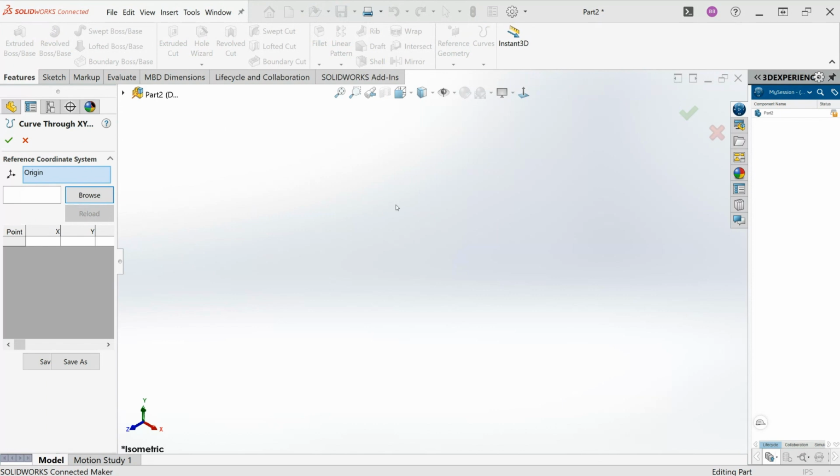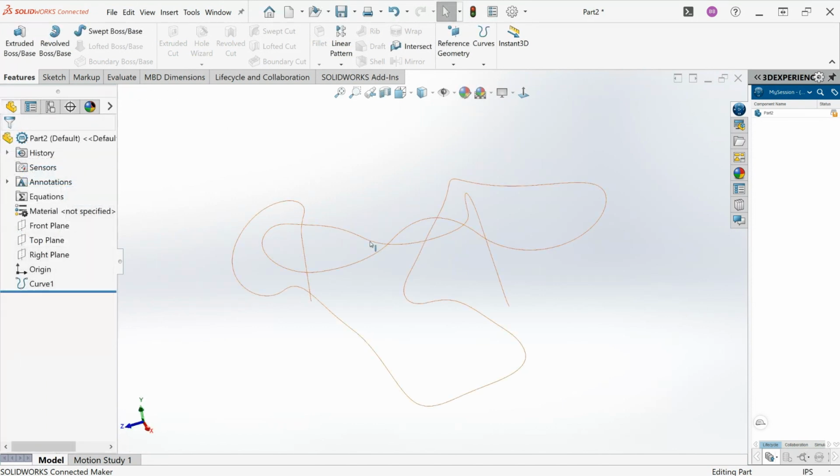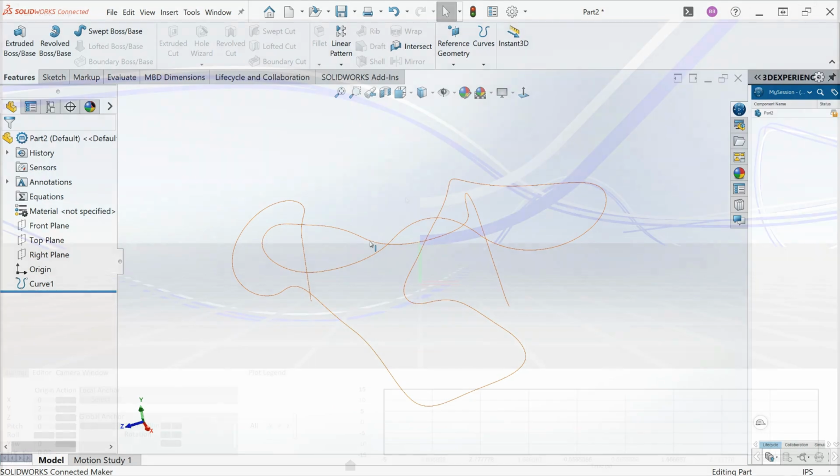The spline is the heart line, and the 2 references are the track. For each of these files, you have to repeat the process and load them into SolidWorks. Once you have loaded them into SolidWorks, it should seem similar to what was made in the program.